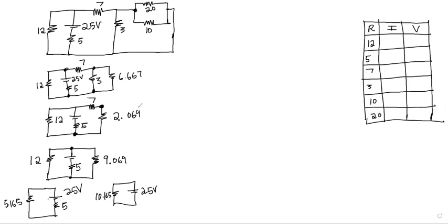Therefore, remember, when we calculate the total resistance, we are going forward. Then when we want to calculate the voltage and the current, we will go back. So what we have done going forward, we will now do a reverse of what we have done. So we will go back. Now, let's start with total current. We can't get everything if we don't have total current. So total current, IT, is equal to, remember Ohm's law, 25, which is the voltage, divided by the total resistance.